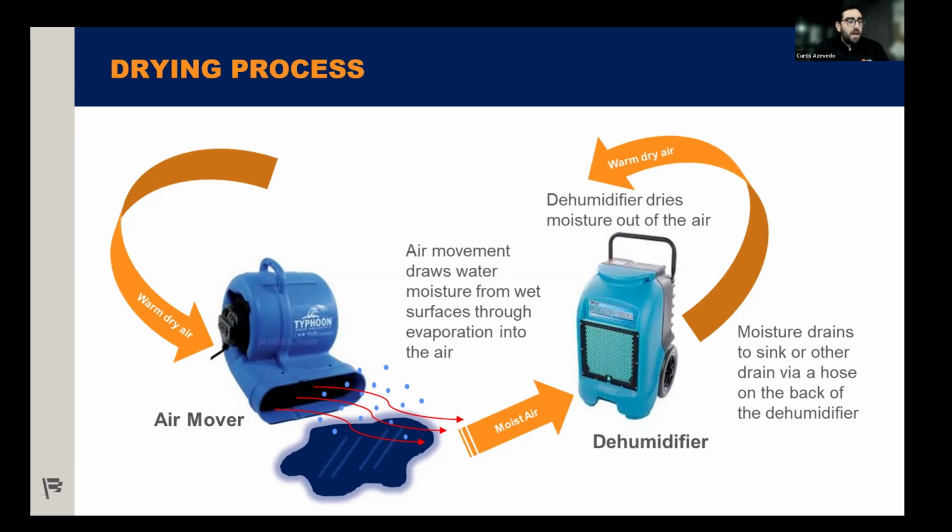So if you have a bathroom where we have a tile floor and there's a major loss in there that's not dealt with appropriately, that could have a lasting impact on the hardwood flooring in that same unit as well, just from the moisture retention on the subfloor. Making sure that we are constantly putting dry air through the drying process is a critical part of it.